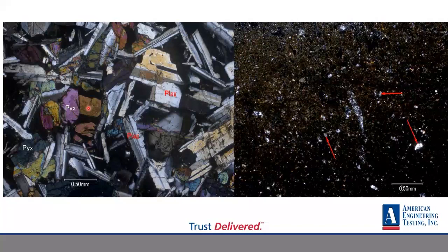So this one is, I did a C295 on this aggregate, and this was a nice quarried basalt aggregate. Started seeing these nice angular fractured particles, which you would expect out of a hard rock being crushed and produced. Well, then I started finding all these soft, rounded particles, and I made a thin section of it, and it was this image on the right, and it was like a mudstone or shale or something. And I was like, what the heck happened? So I called the geologist. This is from the West Coast. You know, sometimes for these quarries, we don't get the location of these quarries.